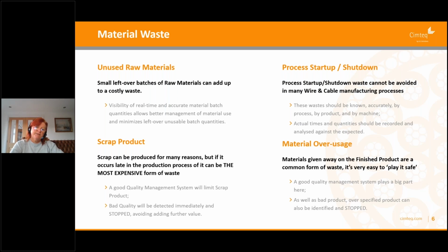And at this point as well, if this happens early on in the process, so we're making a bigger cable than we need to be, every process further on is just going to get worse, because you're starting off with a bigger cable and you're going to have to use more material to make the next process in spec. So this has to be stopped early on and not let it progress.